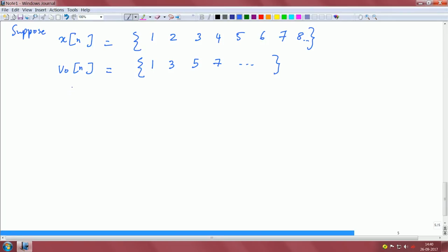Now V1 of n is basically you take a delay element and then you downsample, right. So basically at the first step you may have some value, then you will end up with 2 4 6 8 dot dot dot, right. So basically if you introduce a delay, the reference here would have been some element in the past before time 0, let us say that variable is x, right. You will have x, if you delay that you have x 1 2 3 and so on. Now if you downsample you get x 2 4 6 8, clear. So this is a dummy variable indicating some value that would have been possibly before time equals 0. So this is basically time equals 0.